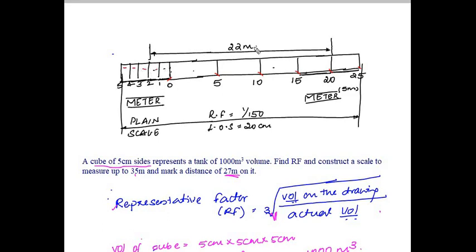So now on this scale I am going to mark 22 meters. Okay. So directly we will go to 20. We don't have 22 directly. So on the main scale, on the main division we will mark 20. So from 0 up to here it is 20 meters. Then you have 1 meter plus 1 meter, 22 meters. So you can just go to the numericals 20, and on the subdivisions you can go to 2 and mark it. Now this length is representing 22 meters.